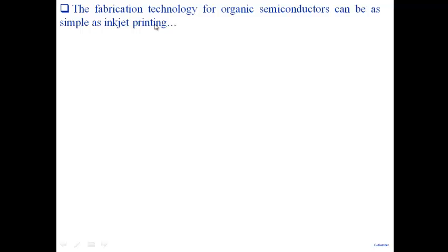As an example, we have in this center also inkjet printing. Now imagine that, why imagine? I'm saying this is happening. So you have a glass substrate or a plastic substrate, and you are all familiar with your inkjet printers. Instead of those cartridges with red, green, and blue ink, I put solutions, inks. For example, I could put a conductive ink, for example silver ink. What is silver ink? It's made up of silver nanoparticles dispersed in an ink form.